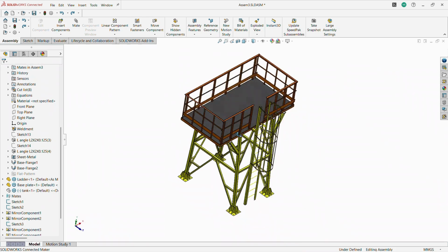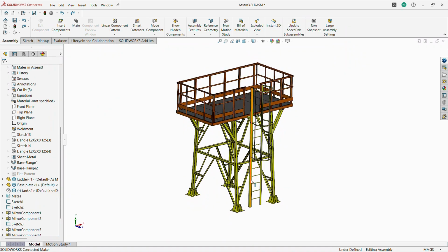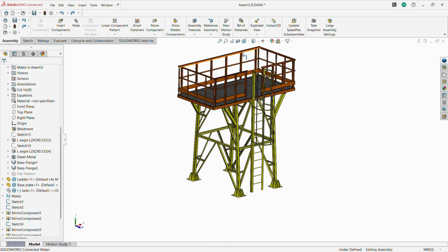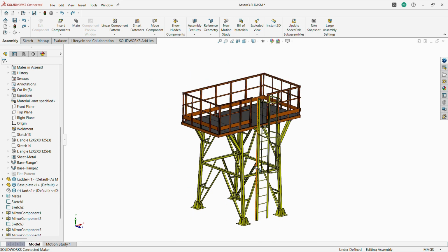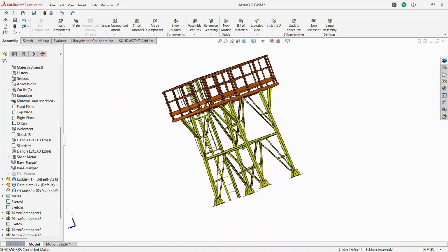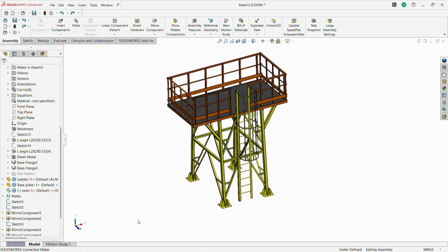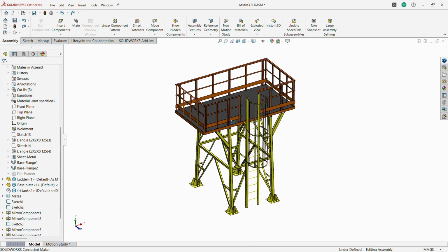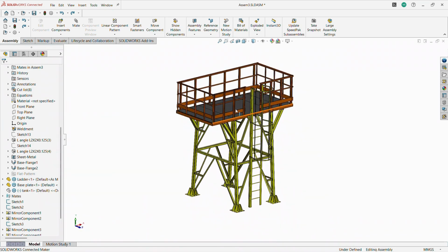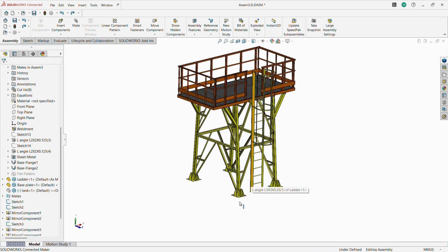Sheet metal is important for designing any kind of structural products. What are the things you need to consider while designing sheet metal? K factor, bend allowance, bend directions, what the material properties are, what thickness I need to give, what bend radius I need to give to design this product, and how it is suitable to design weldment structures.